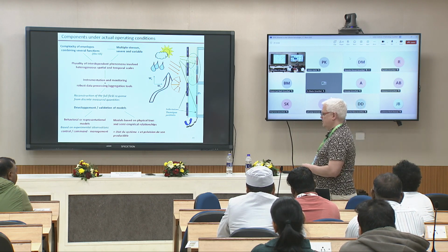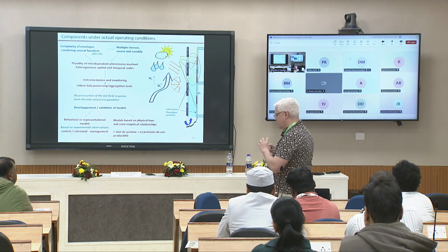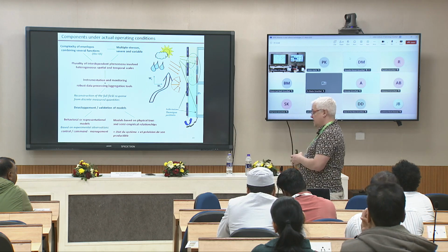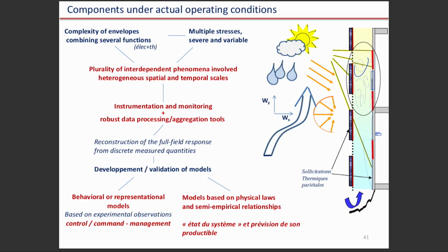So wind and natural ventilation is complicated, and you have to know your environment very well, where and what the dominant wind is. You also have the thermal aspects, because for the chimney effect there are only two ways to naturally ventilate: to use the difference of pressure, so the wind, which is very strong, and to use the difference of temperature with height, so the difference of density.